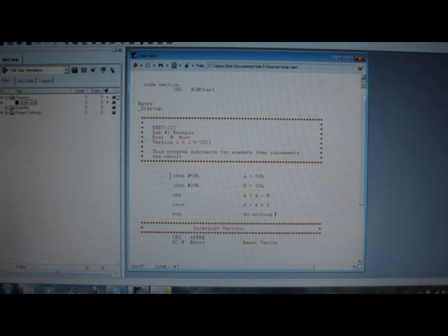And then the program actually starts here at this statement LDAA #50. That says load accumulator A with the value 50 hex. And notice that I have a comment over here, A equals 50 hex. Also notice that I've tabbed over from the left side. You need to do the same. Tab over about the same distance as we had initially with the assembly language program that was deleted.